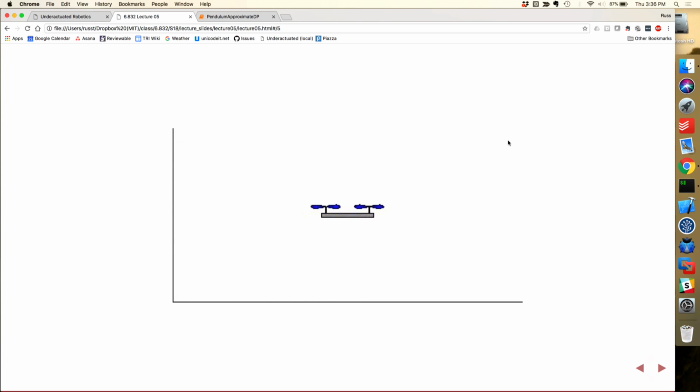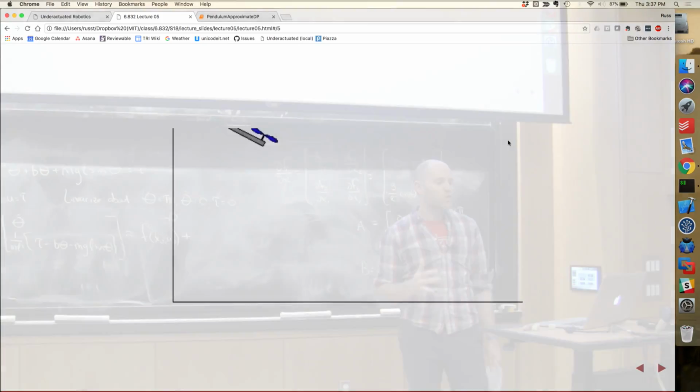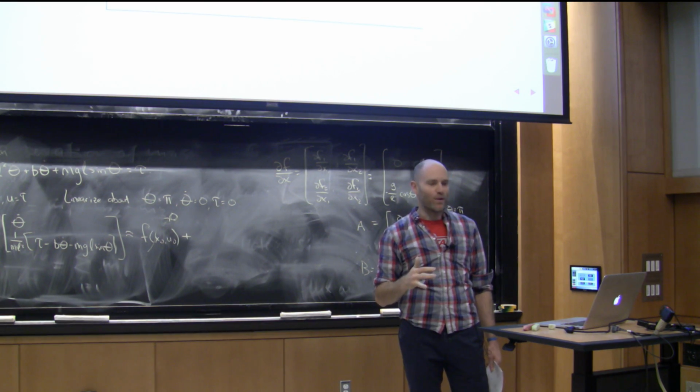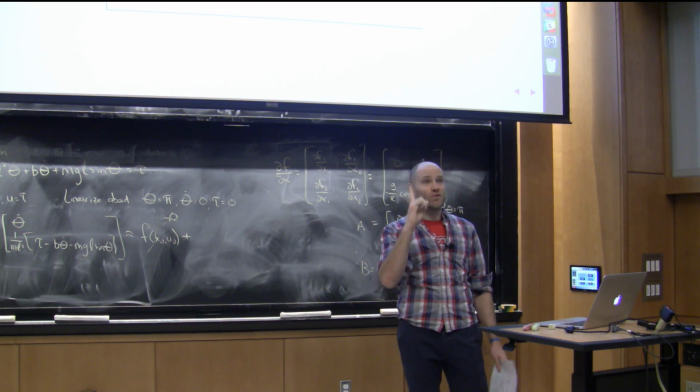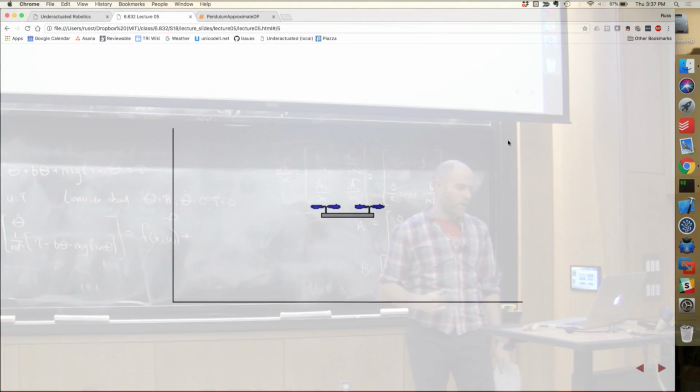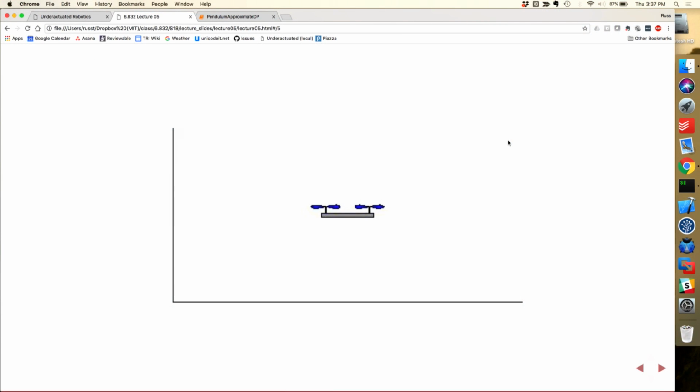And now quadrotors actually, the reason they're amazing is that basically outrunner motors came online, and you could put a ridiculous amount of thrust out of these little motors, and most quadrotors today are overpowered, and they have a thrust to weight ratio that is way, way, way bigger than 1, and they actually can recover from all kinds of initial conditions like this. And most people use LQR to design those controllers. Okay, and it works in 3D too.